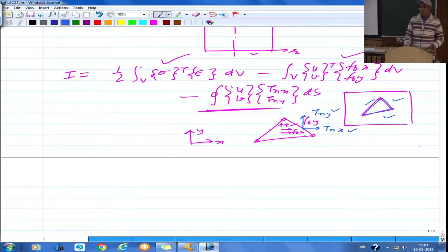So this is actually internal force vector, essentially you are accounting for the internal forces. But when you solve overall problems, because on some boundaries you might have some externally distributed force prescribed, you can also take care of that through basically this term. Otherwise, when the element is inside the domain, it is actually internal contribution to potential energy from the internal forces acting on the boundary of the element.